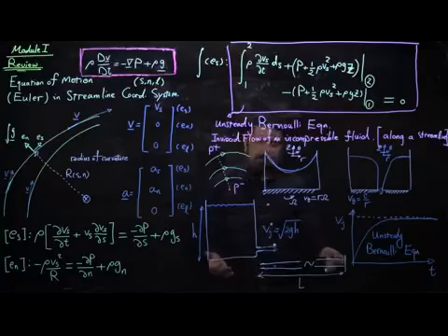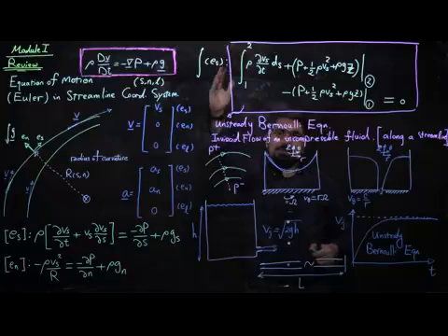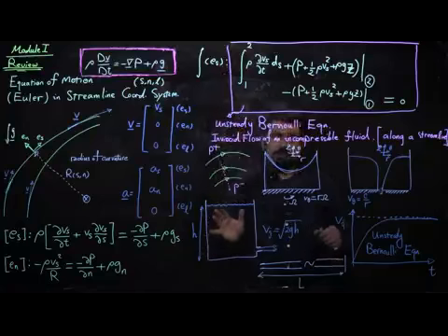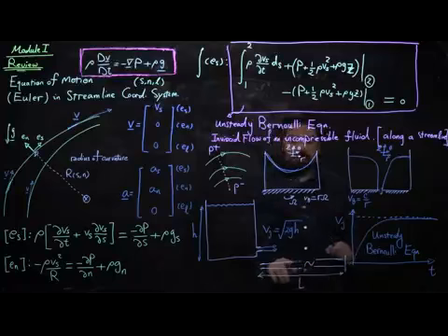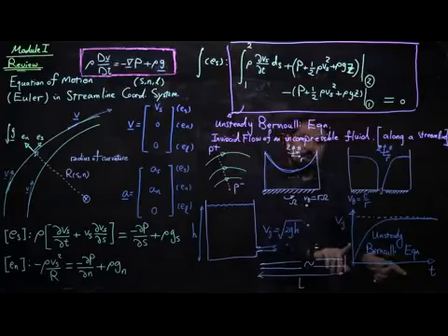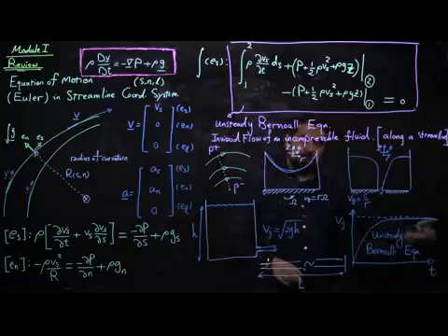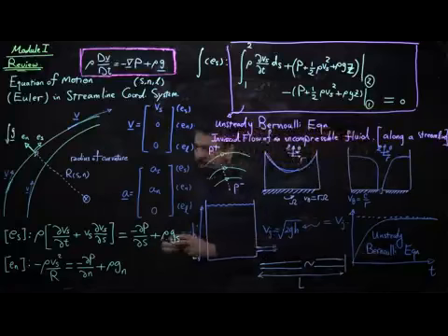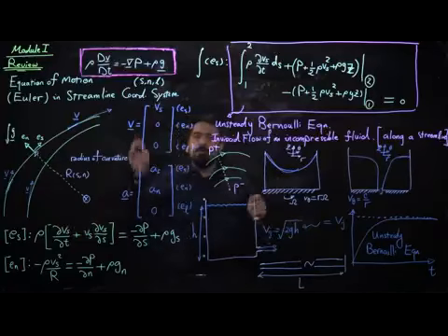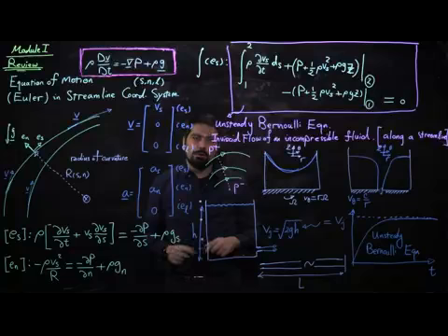But at the same time, if the flow is transient, but transient in a relatively controlled manner, where the shape of a streamline in a long pipe does not change with time, we can use this unsteady form and then find out what would be the transient behavior of the velocity. Initially, it grows linearly, and finally, it reaches its steady state value that is set by Torricelli result being the square root of 2gh.